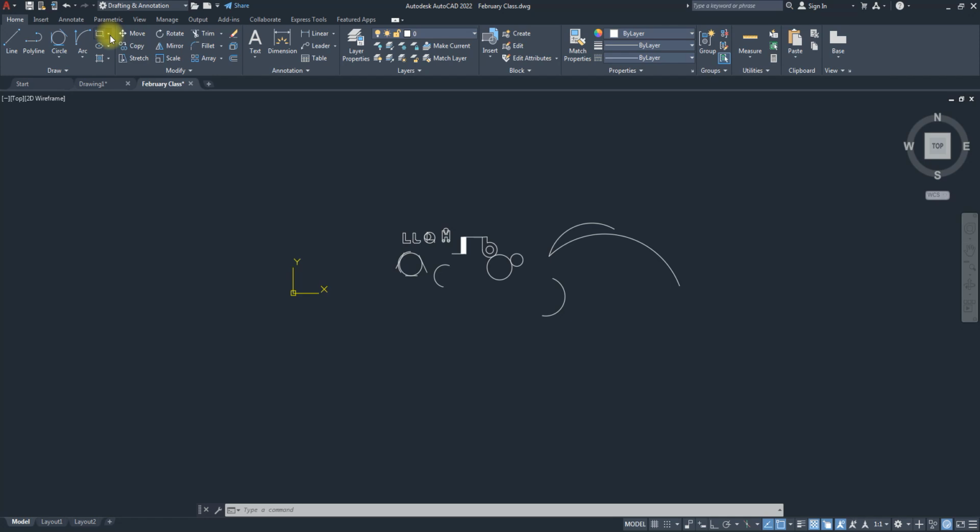All right, the next thing we have is the rectangle. If you click on the arrow beside it, inside you have rectangle and polygon. Let's look at rectangle first. The shortcut for rectangle is REC, R-E-C. If I click on rectangle, it tells me to specify the first point. The way a rectangle is created is by specifying a diagonal, just like when you measure a TV, the inch value you talk about is the diagonal length. So for you to create a rectangle, it asks for the first diagonal point and the other point.